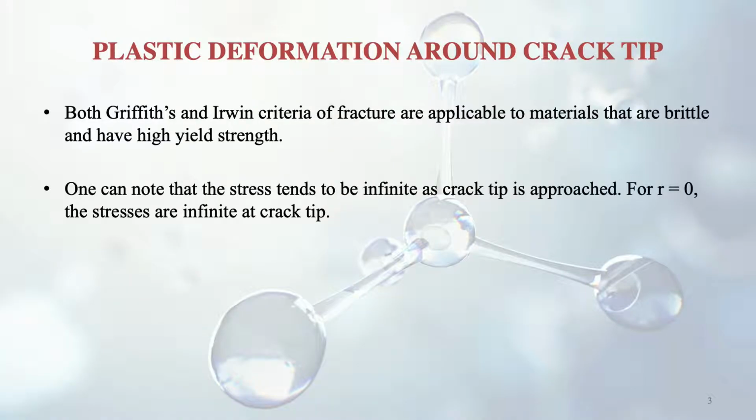is approached. So as you move near to the crack tip, very near to the upper portion of the crack, the stress will be very large. You can say infinite. For r equal to 0, the stresses are infinite at the crack tip, meaning that if the radius of curvature of that crack is 0, then the stresses will be infinite, because the area of cross section is almost 0, and the area comes in the denominator, so that will become